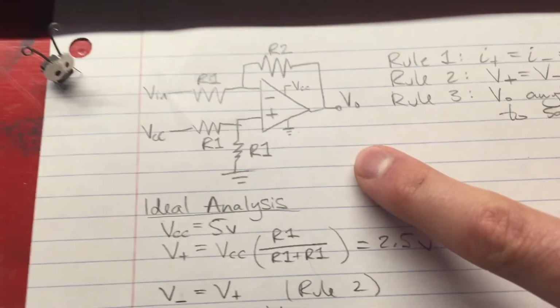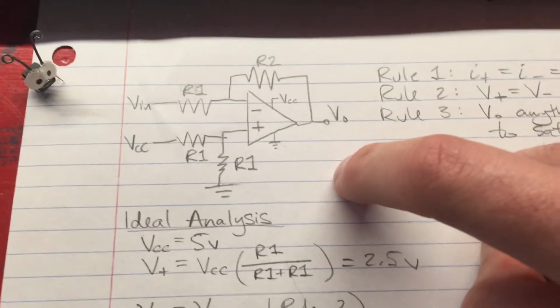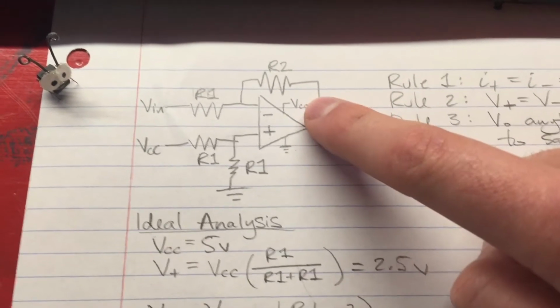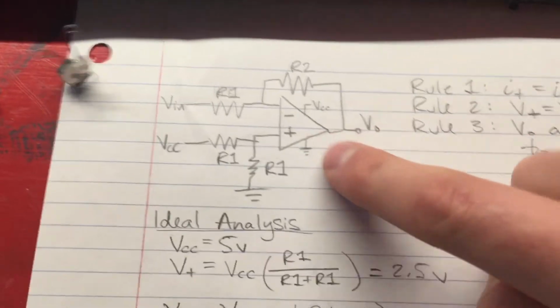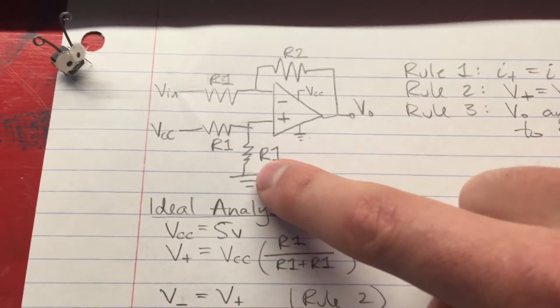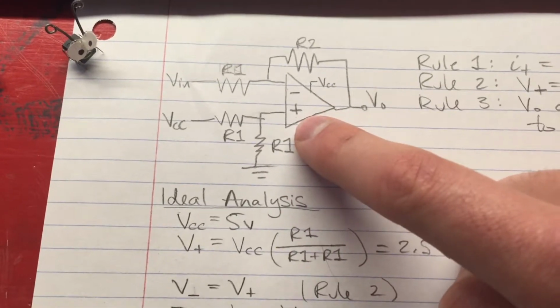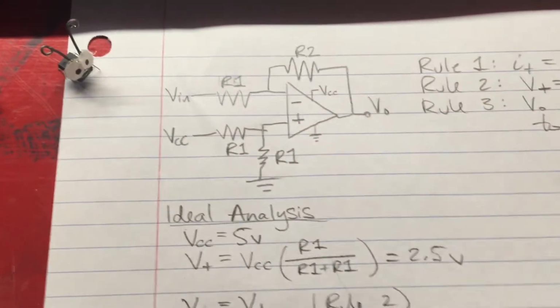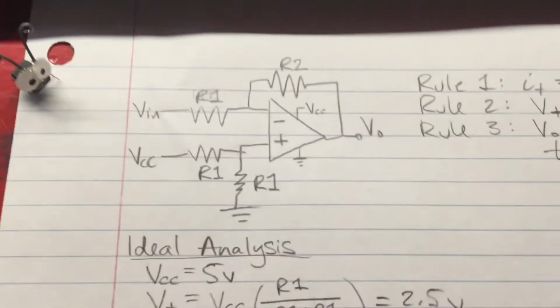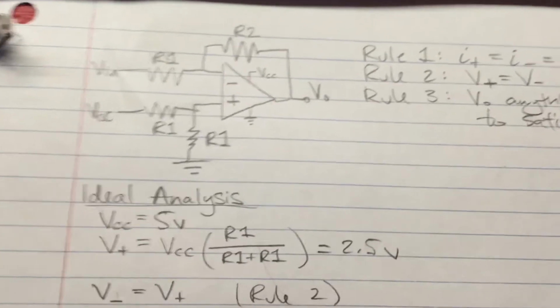For exercise 3, I built an inverting amplifier as shown here. Since I'm using a single-sided voltage supply of 0 and 5 volts from the Arduino, I'm going to use a virtual ground made from a voltage divider to set the voltage on the non-inverting pin to 2.5, which is halfway between the supply voltage and ground.